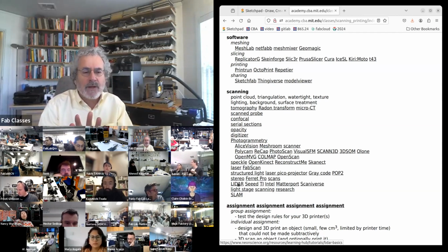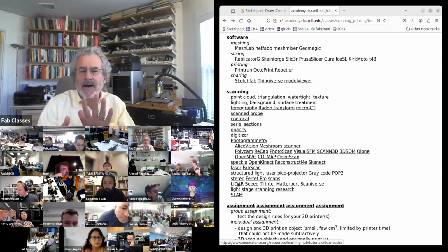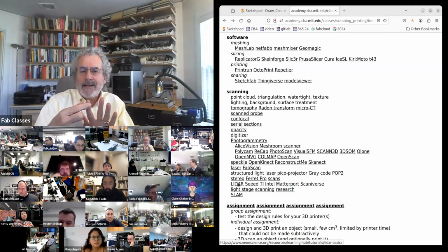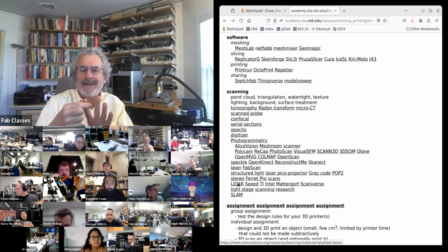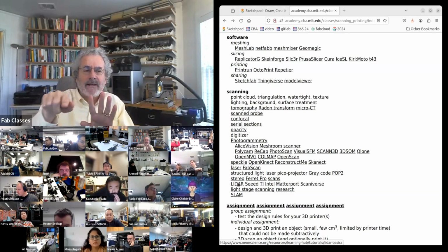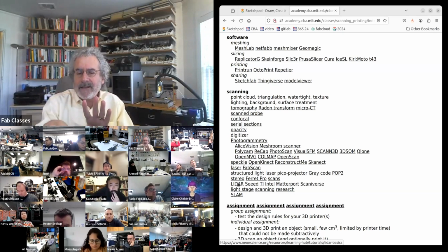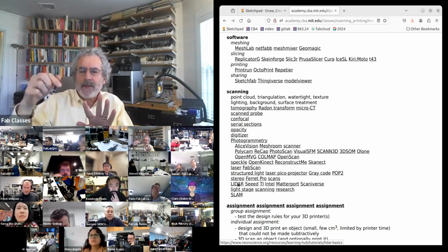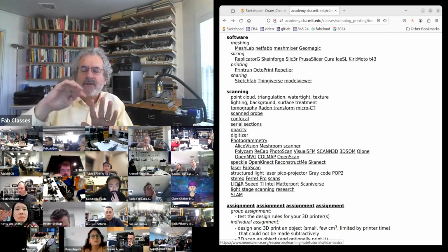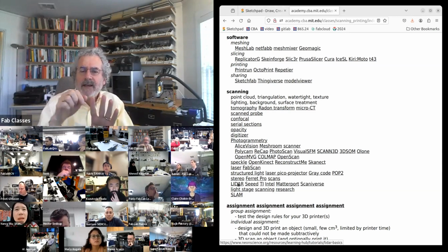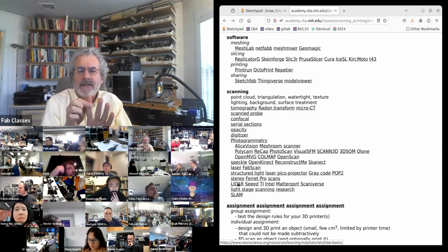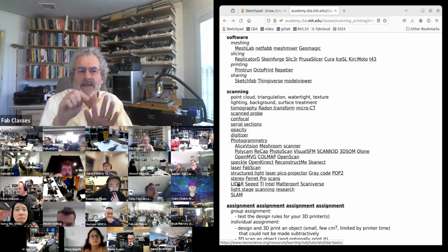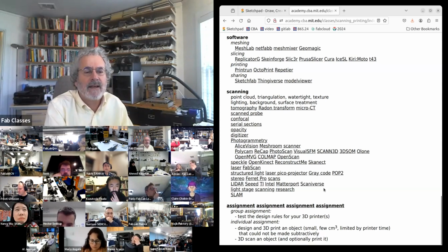And the most interesting one are cameras. So a LiDAR camera, each pixel is like a little radio receiver. You send out the light, but you modulate the light with a waveform. And then each pixel measures the modulation, the phase of the modulation. And by doing that, the pixel is measuring not just image, but distance.